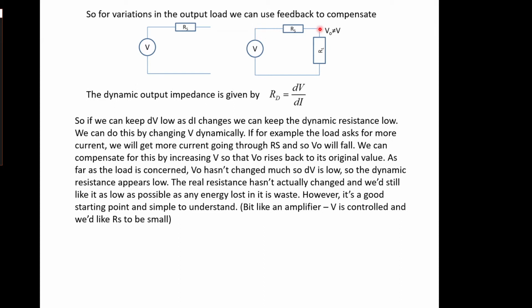It's just maintaining this voltage at a given point irrespective of the current, and that translates to a dynamic impedance that's really low, even if this real impedance isn't low. That's really what we're just trying to say. It's a subtle point, and it's not that important in the great scheme of things, but that's how we can get an effective 0 impedance when the real impedance that you would measure is not 0.